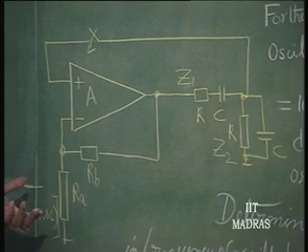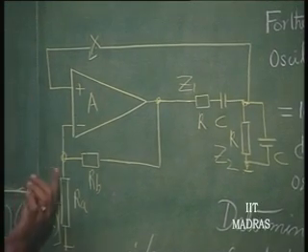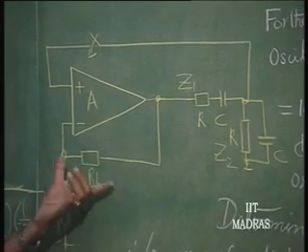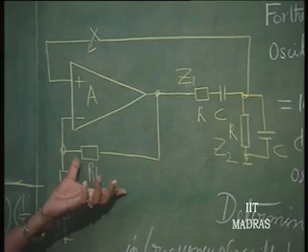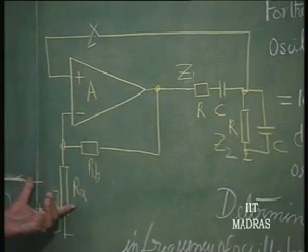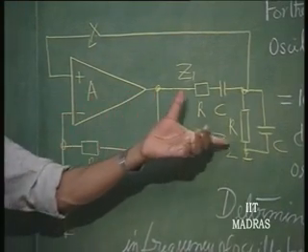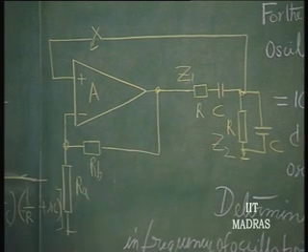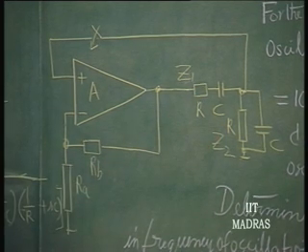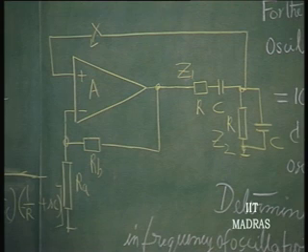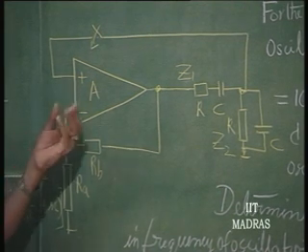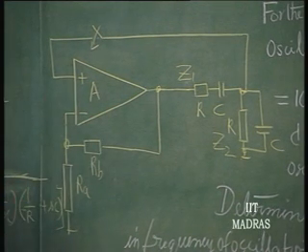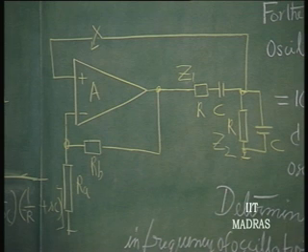The active device that is used, if its phase is frequency dependent, then automatically the compensation has to come from the passive device, and the variation required in frequency of oscillation is enormous for high frequency operation of all these oscillators.